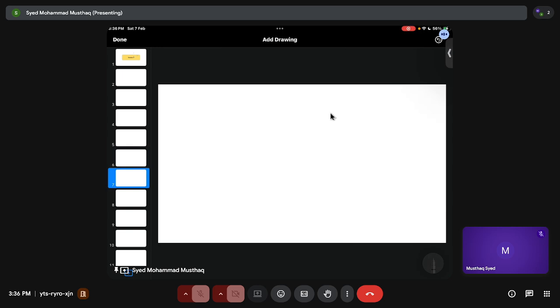There are different batch filters and continuous filters. In batch filters you have leaf filters or tray filters, and in continuous filters you have rotary drum and disc filters. You can look up the mechanisms also. The basic principle behind them is this: you apply pressure, some goes through, some will not, right?